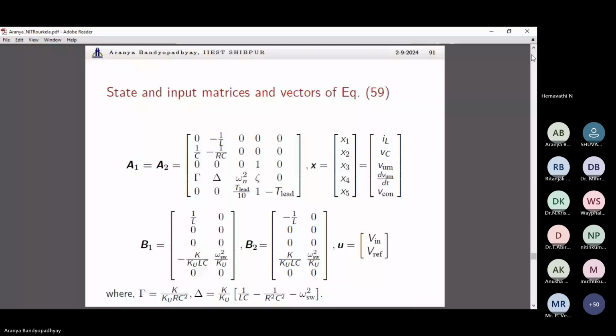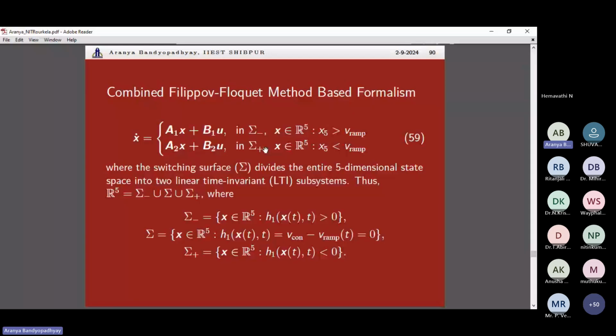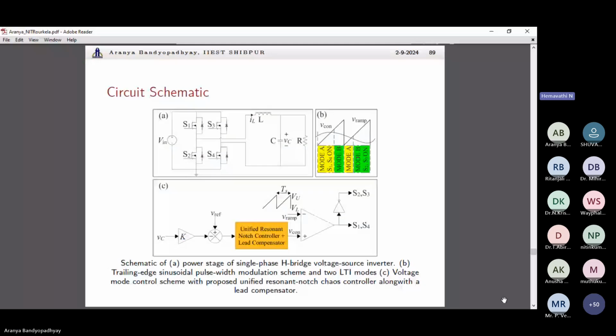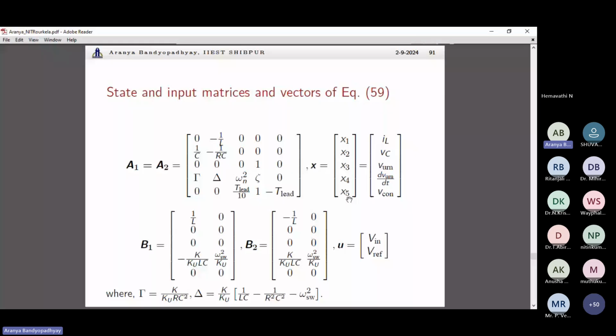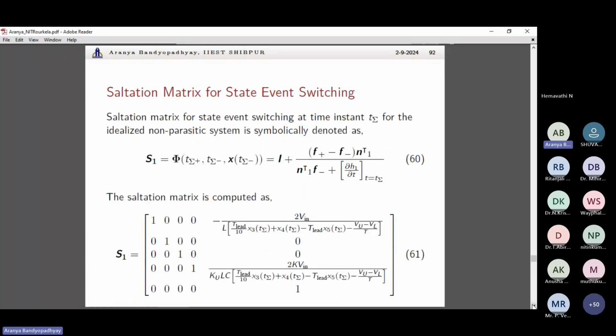But in totality, this manifests as a fifth order system. We basically wanted to make something which would mimic the combined behavior of a proportional resonance controller with a notch filter. So can you see that within a reduced order, we have to some extent been able to meet the same type of objective.